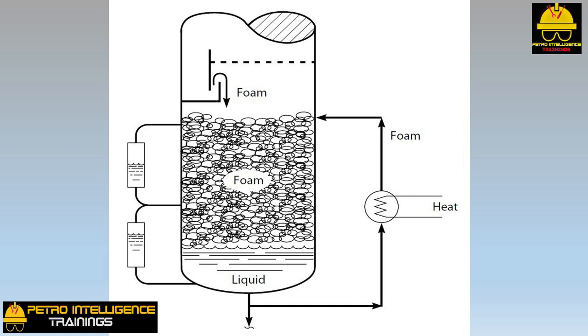Of course, the flow from the bottom of the tower is going to be a clear liquid. Foam cannot be pumped. But there will always be some ratio of foam to clear liquid in the bottom of the tower, and we have no method of determining this ratio or even the density of the foam. Well, if we do not know the average specific gravity of the foamy liquid in the bottom of a tower, how can we find the level of foam in the tower? The unfortunate answer is that, short of using radiation techniques, we cannot.